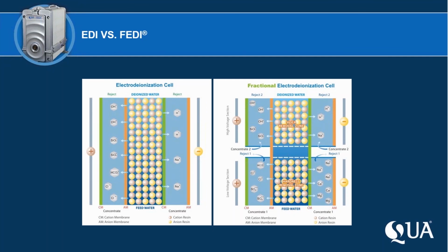But over the years, it's been developed and been known that the flow velocity isn't similar to a membrane process like an RO. Anyone skilled in designing RO systems knows that you need a certain velocity in your reject or concentrate compartment so you don't form scale on the surface of the membrane. EDI is not, I'll say, a pressure membrane system. It is not a filter.